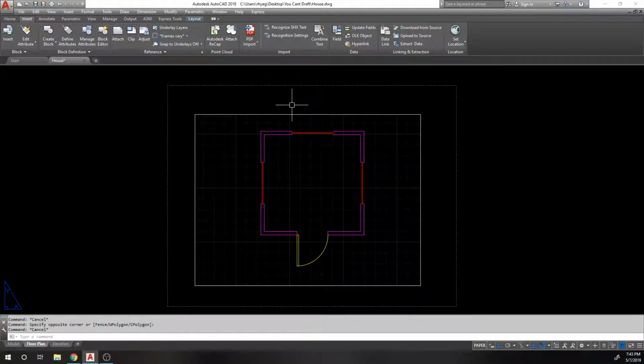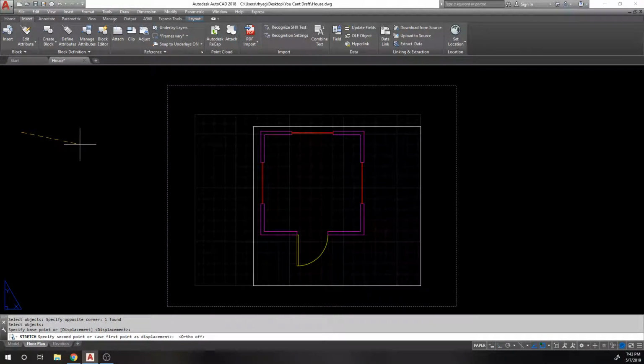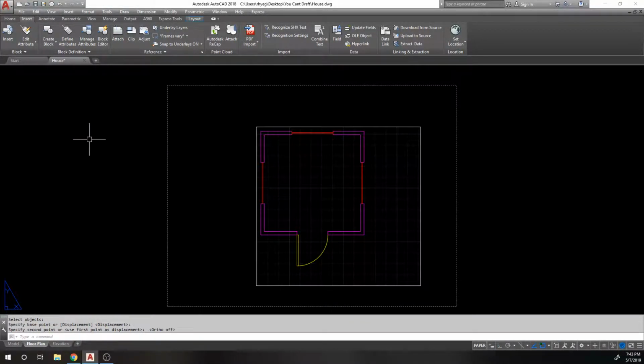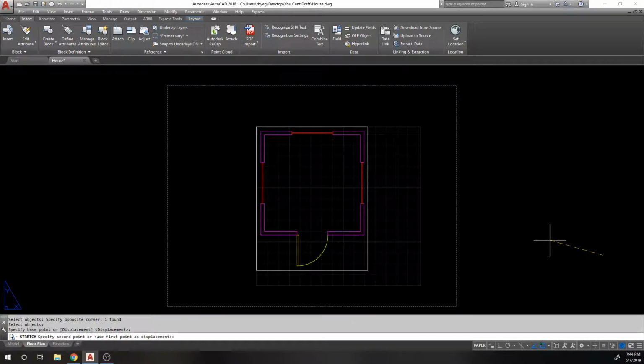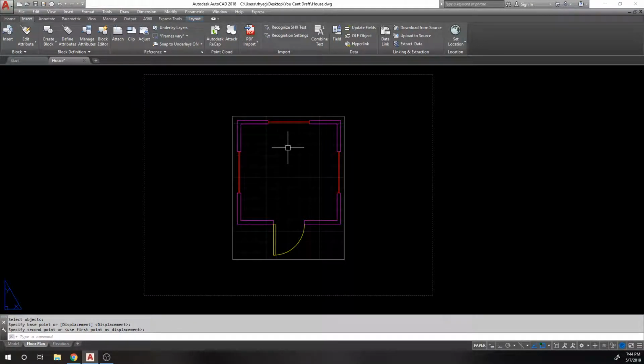All right, now that I've got my viewport, what can I do with this? What can I do to flesh this out into a drawing? Well, first, let's give ourselves a little bit of working room in the paper space. I'm going to bring this viewport close to my object. I don't need to have all kinds of extra space. I just want to have that viewport lined up right to the edge of my object. From here, now I can start annotating and dimensioning.